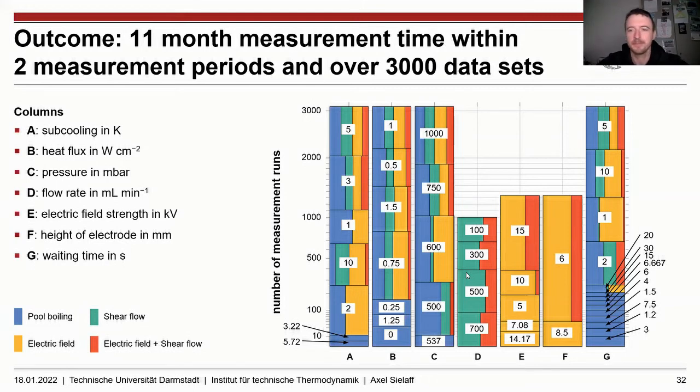Hello, Vladimir. Axel, thank you for a really nice talk. It's great joint work. I have a question about the operating parameters which you used. The maximum heat flux was only 1.5 watt per centimeter square. What about high heat fluxes, since most of the devices used both on ground and in space deal with much higher heat power? And the pressure range is not so wide. It will be very interesting to see what happens at extra low pressures, when the bubbles have extra large sizes even at normal gravity. Maybe you plan some further experiments on that.